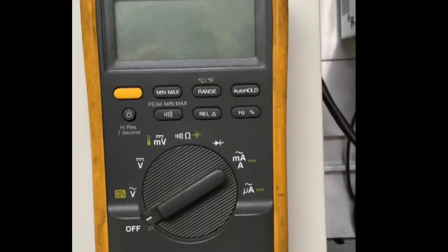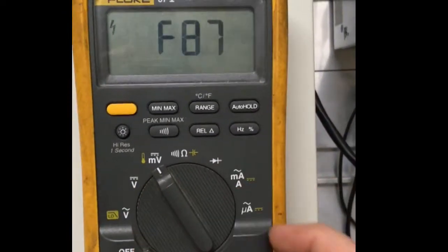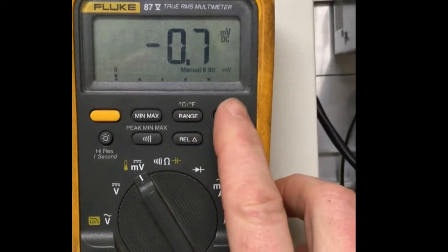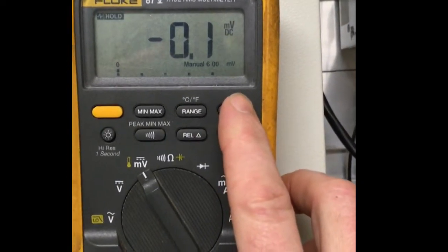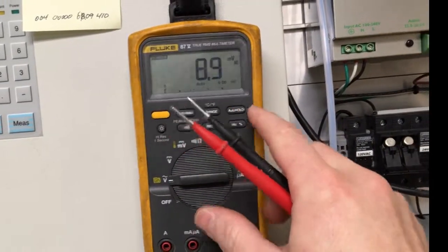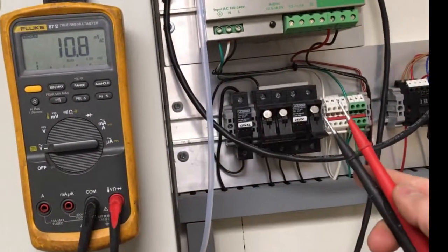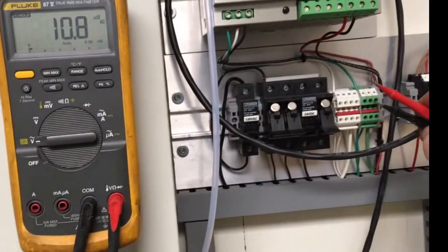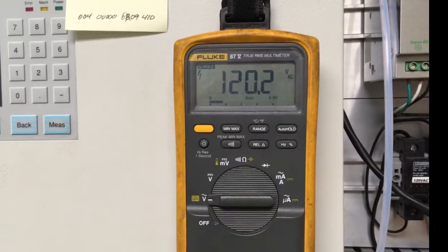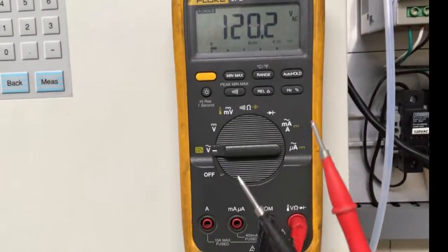The auto hold button takes the current measurement and makes it a static value displayed on the screen. This is useful if you are trying to record measurements at specific intervals, buying you time to record the value. The value, however, is not completely static. Once a new stable value is measured, the display will update, producing an audible tone to signal the occurrence.